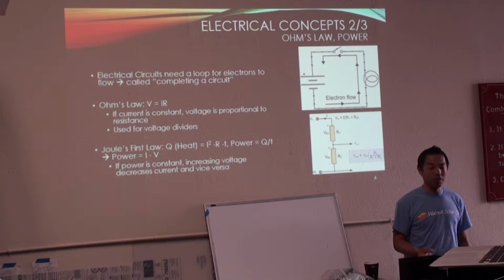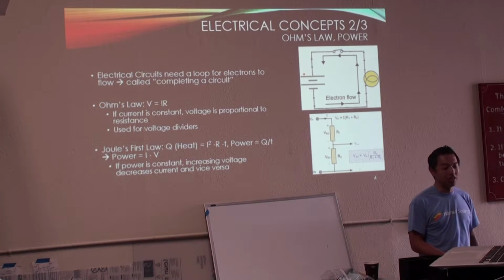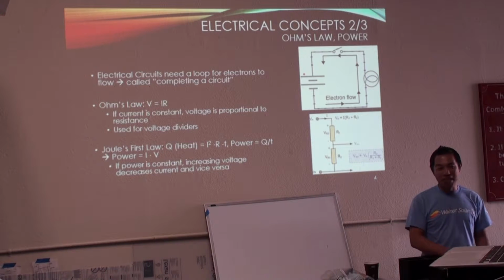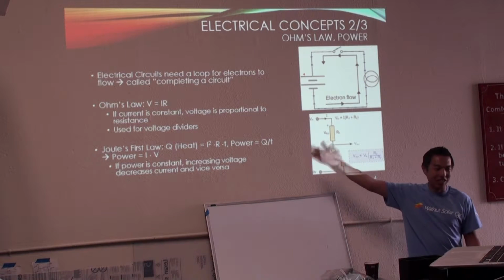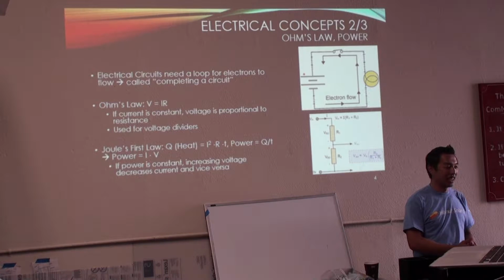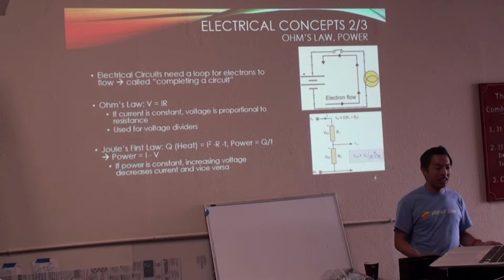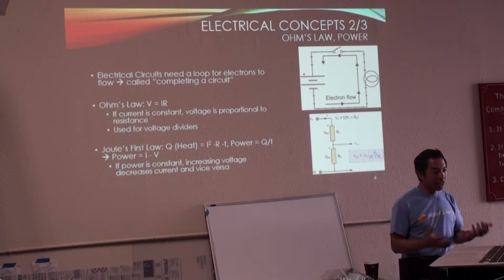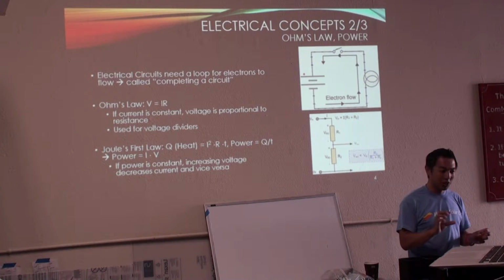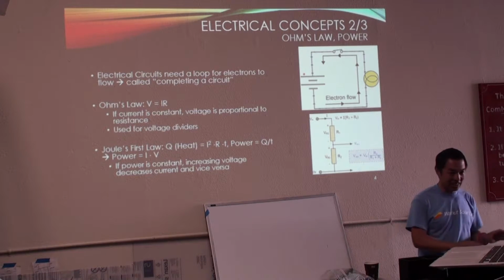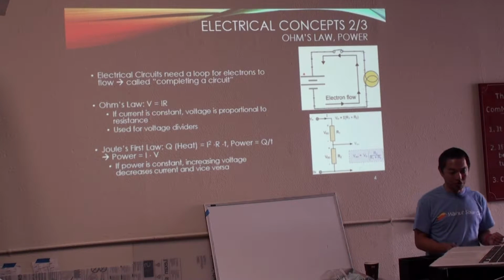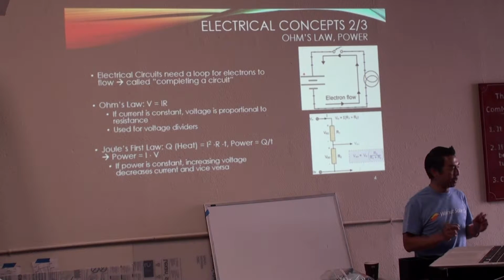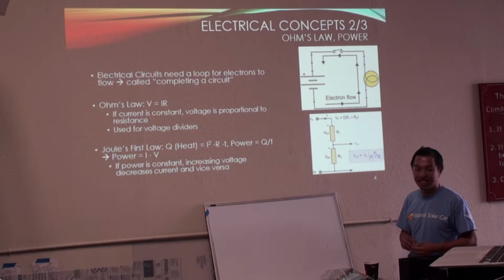If you have an improperly sized cable, for example, and you touch it and it's hot, you are basically losing electricity because of this Joule's first law. So when we go around and we want to do optimizing, or if we have some issues that we're trying to figure out, you will say, okay, is there heat somewhere? You shouldn't have that problem because you properly sized the cable in the first place. And we'll talk about that in a second.